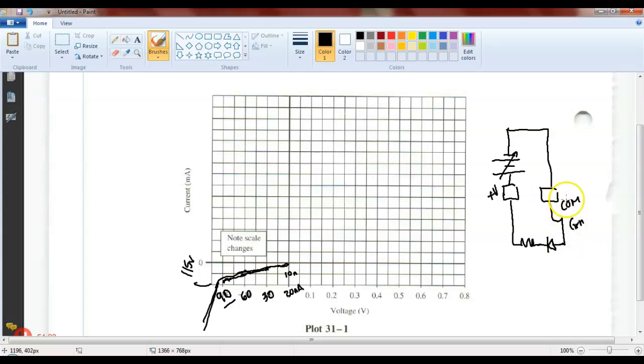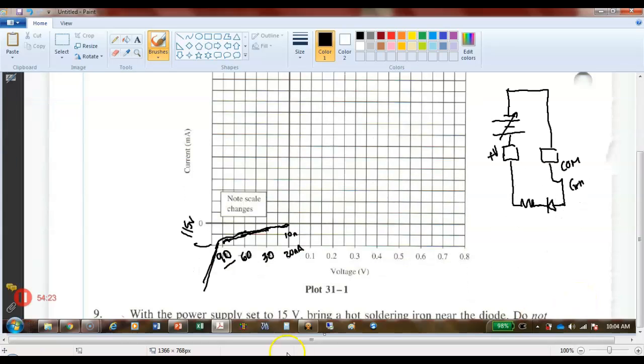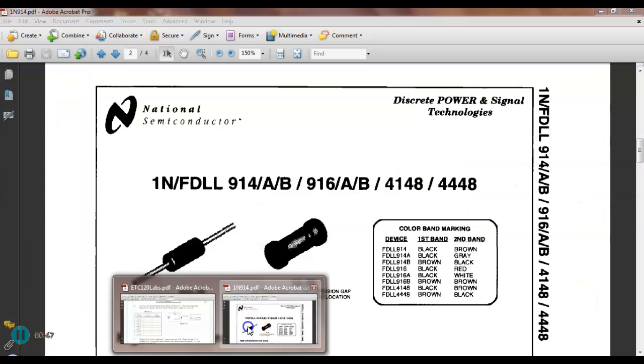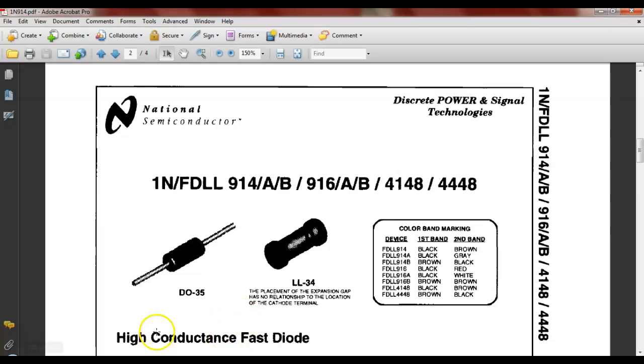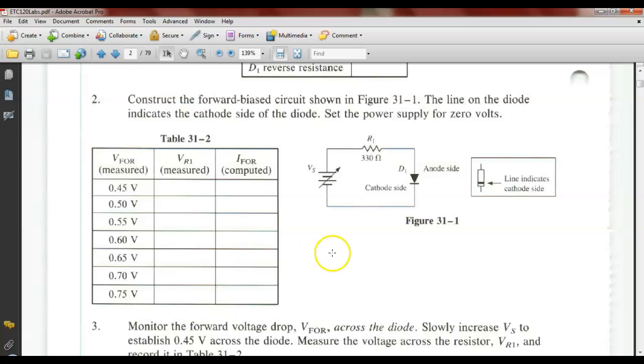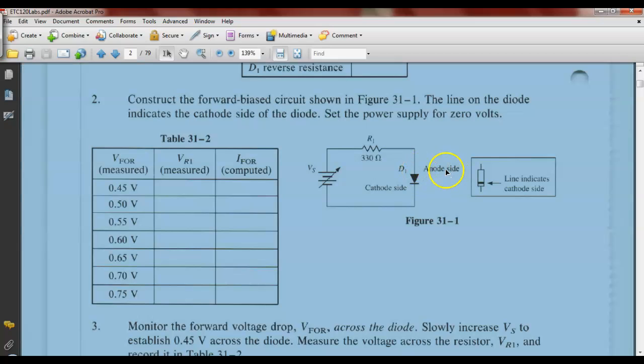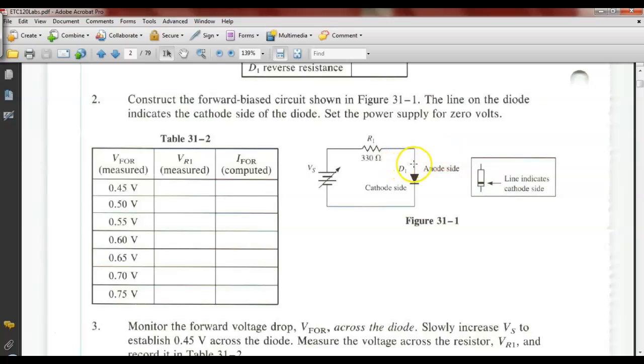And then, of course, like I said, you'll take your maximum current, which will probably be at 0.8 of a volt. So you're going to make measurements. One meter, you have to move your meter. First of all, we're going to use our meter to measure across the diode. I can't draw on this, Rich. I'm going to use my meter to measure across the diode.